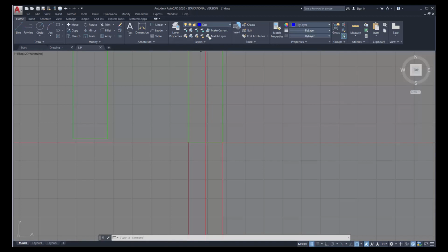Let's take a look at our drawing. I'm going to switch to the concrete foundation layer. I'm going to offset my first step. Now you'll notice that it's a solid line above grade, and then below grade it's a hidden line. So the first 6 inches are solid. So I'm going to select offset, type in 6 and enter. Click on the line, click on the side.